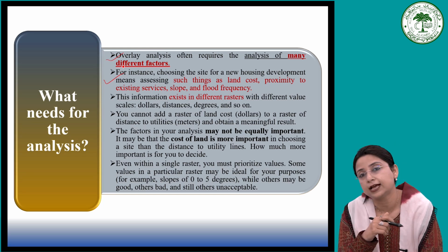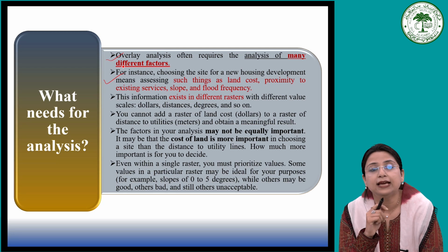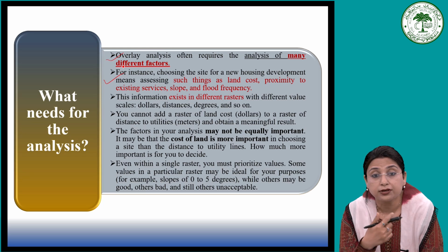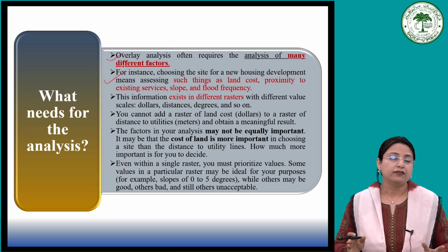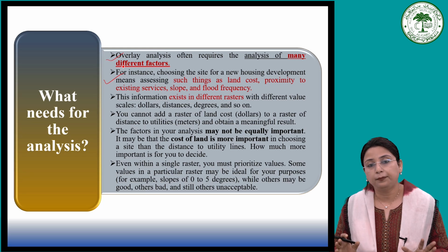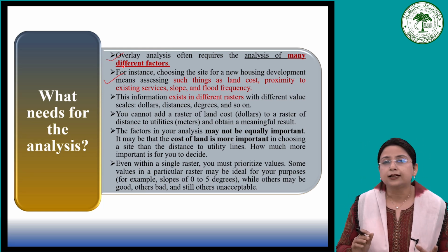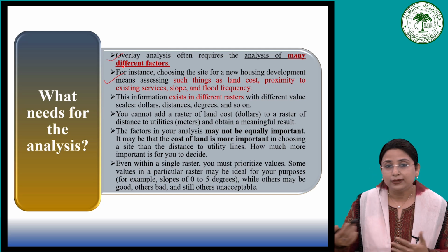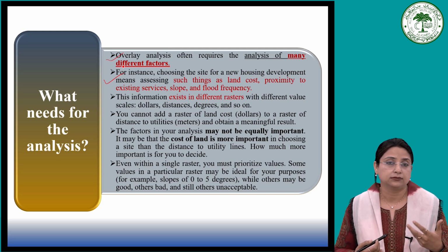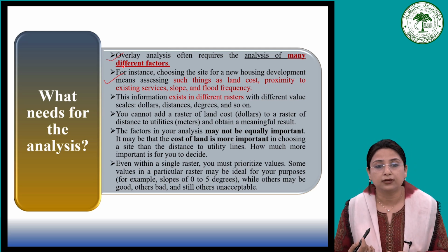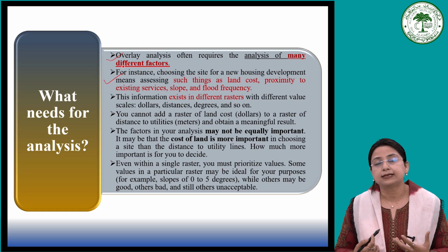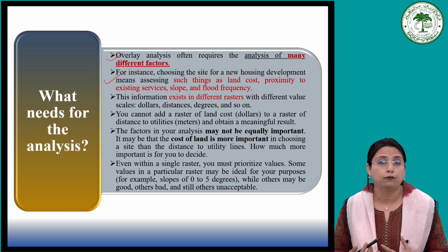If we want to choose a site for a new housing development, we can consider factors like the cost of the land, one of the very important factors, and the proximity to existing services, because whenever we choose a particular place for new housing development, we consider what the accessibility will be to certain services, amenities and facilities, what the slope of that particular place is, and whether the place is prone to flood or not.